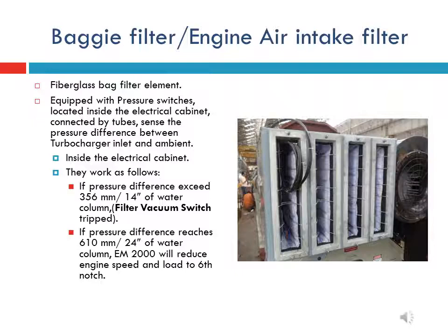Due to less positive pressure in the airbox, the scavenging of burnt gases may not be proper and the burnt gases may enter the airbox through the air port also. In this situation, firing may take place in the airbox in the worst cases and back pressure may also develop, which may cause surging of the turbo supercharger.